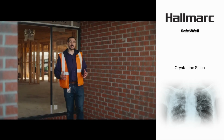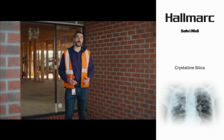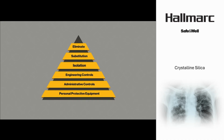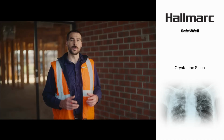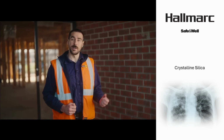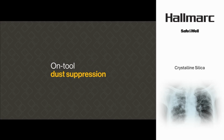When controlling risks associated with respirable crystalline silica, it's important to follow the hierarchy of control. If elimination, substitution, or isolation aren't possible, engineering controls should be used. The two most common forms of engineering controls are on-tool dust extraction and on-tool dust suppression. This video will talk about on-tool dust suppression.